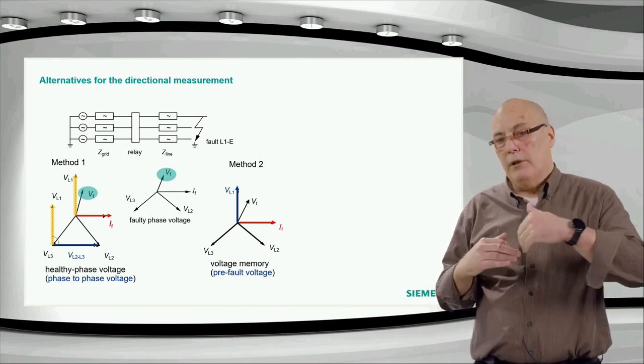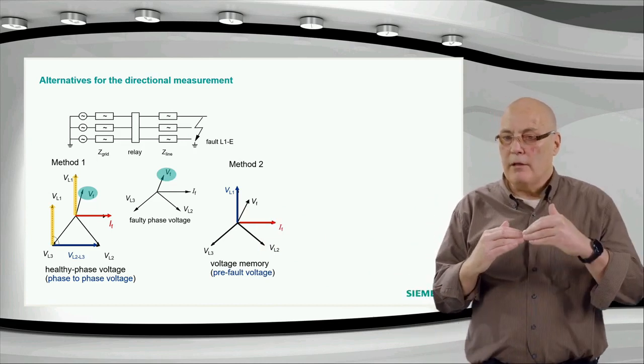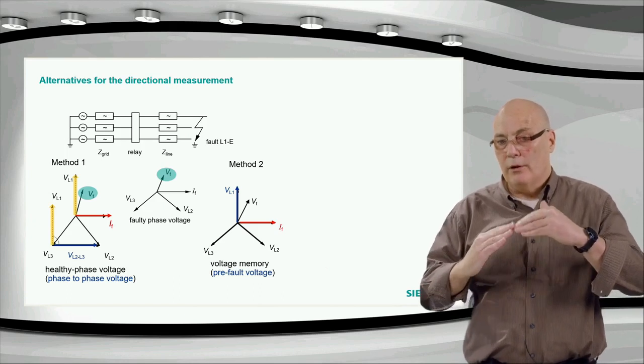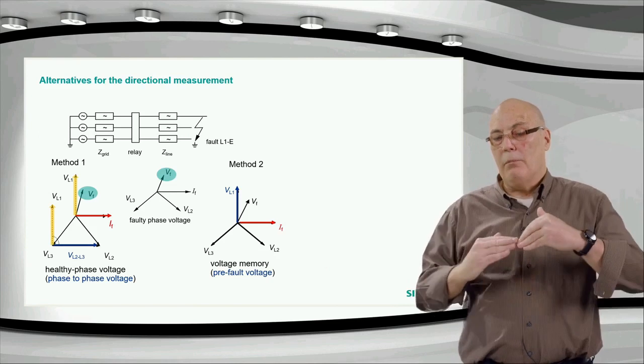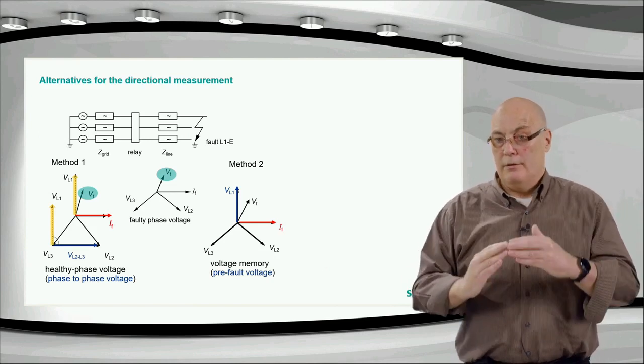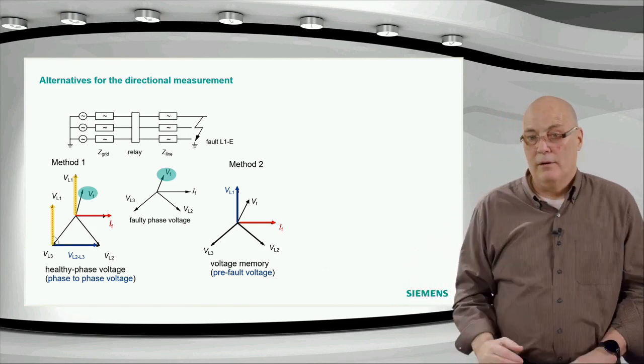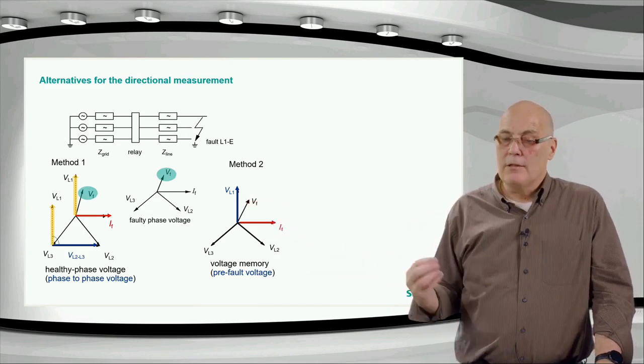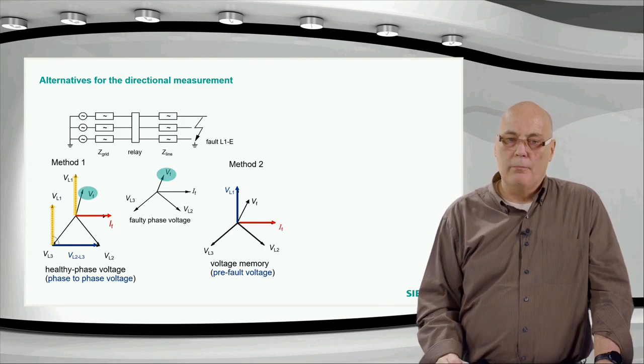You see, that's why you see the reach boundary going 30 degrees into the second quadrant and 22 degrees into the fourth quadrant. The directional boundaries are tolerant. They are not restrictive around the fault. To make allowance for any influences like this, it's not critical. So that is an important thing.